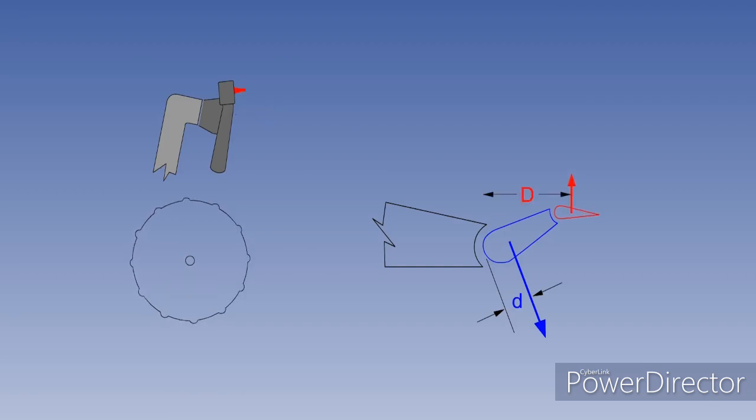Making this trim input moves the trim tab down, away from neutral with the elevator. As the trim tab moves down, an aerodynamic upforce is generated on the elevator trim tab. Eventually, the moment from the trim tab becomes equal to the moment from the elevator. The stick force has been reduced to zero and the aircraft has been trimmed. Please note, when using a trim tab to trim an aircraft with a forward CG position, the cockpit control remains displaced aft from neutral.